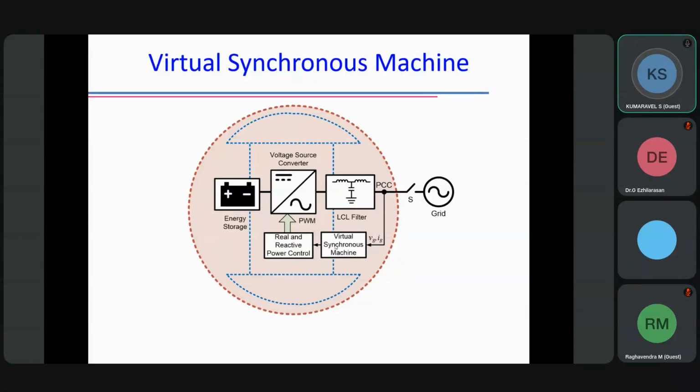Now, what are the advantages of a synchronous machine? It rotates at constant speed and is very easy to synchronize. In the synchronization process, we see whether the sequences are matching, A, B, C or R, Y, B. Voltages are correct in magnitude between R, Y, B, all equal in magnitude, and we follow the phase angle 0, minus 120, minus 240, and then we see the frequency is at 50 hertz equivalent.